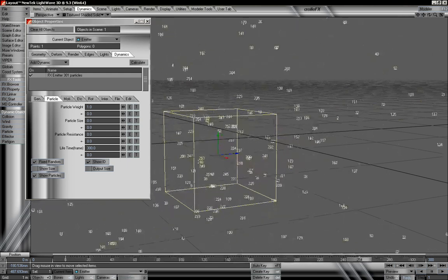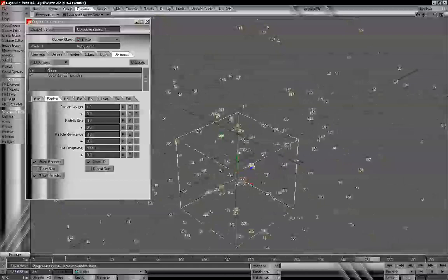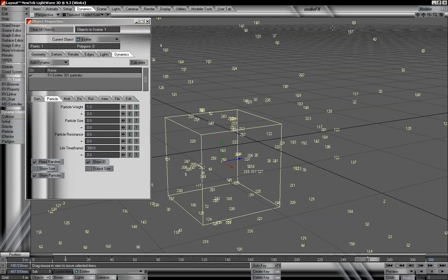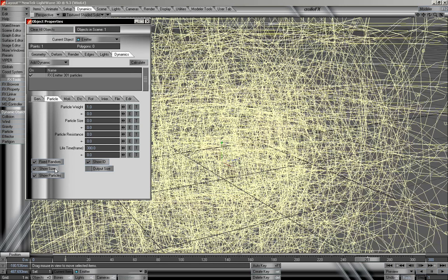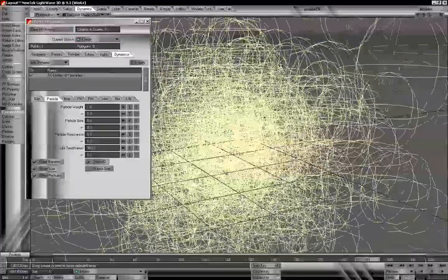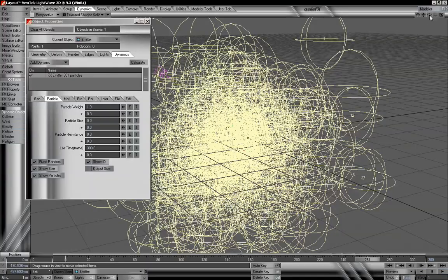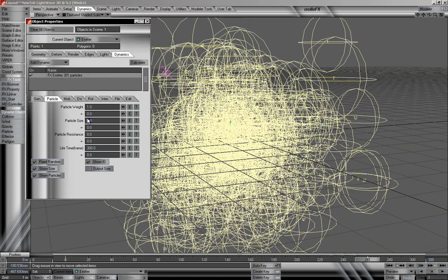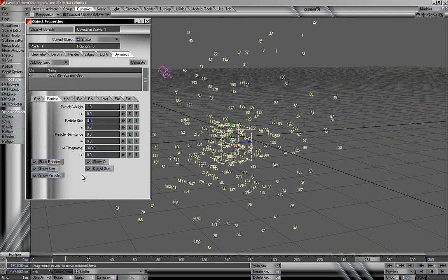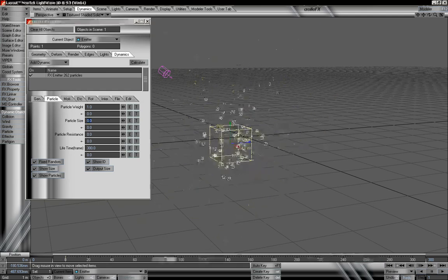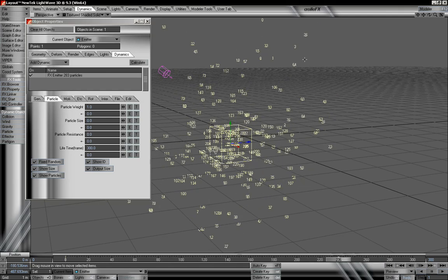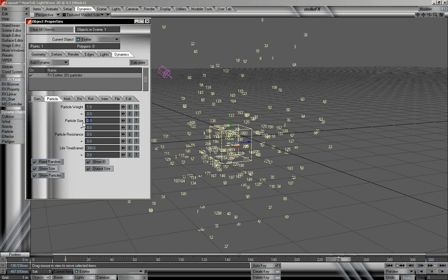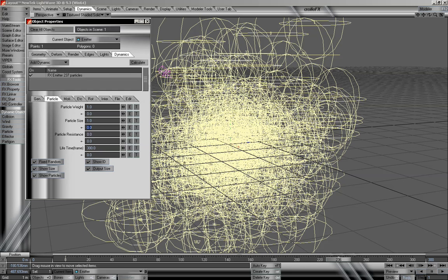And this will be a lot easier to identify some of these different particles when we have numbers on them. What we can also do is set up a show size. Right now our size is set to a default value of 0, and all of our particles are really quite large. So what we would need to do is change this size value and also set our output size. If I turn on output size, that's going to be our absolute value that we have set, and since it is set to 0, we are not seeing the size of our particles. Let's go ahead and change that up to 1, and now that's basically that default we were at before.